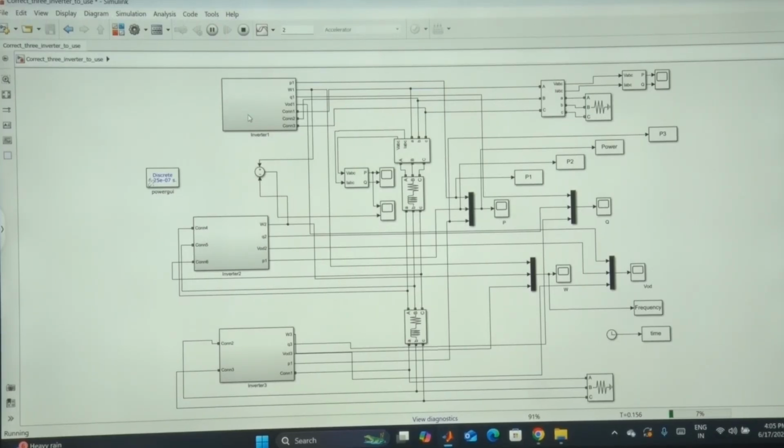In a way, it's good for the system that the frequency change is less. But the effect will be, because the frequency change is less, the integration of omega 2 minus omega 1 dt, that angle will change very slowly. What will happen? Power flow, P equal to EV by x sin delta, that power flow will be slowly increasing.